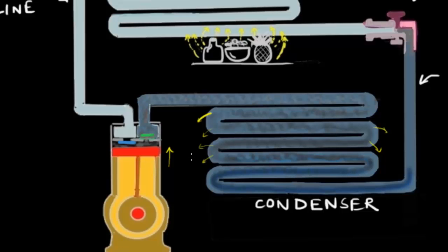So you could even have, let's say, a fan here that will help circulate the air and transport the warm air that is surrounding this condenser coil to elsewhere in your room. So this is basically convection, heat transfer through convection, speeding up the heat transfer here. So at this point you have a high pressure liquid that's coming out of the condenser, and then it goes into what we call the liquid line.